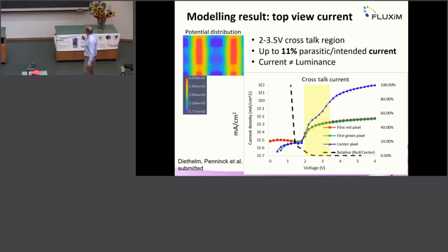And now what is interesting to analyze is the subdomain current. For each of these pixels in the software, we get the current flowing through these RGB subdomains, and then we can plot them. The active center pixel, that's the blue one, has the most current, but the neighboring pixels, the red and green ones, at low voltage, you see here, have a significant contribution of current.